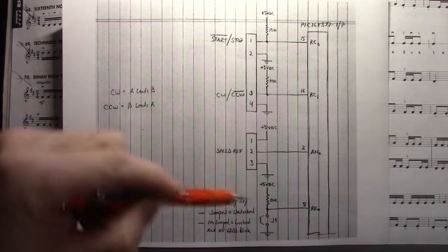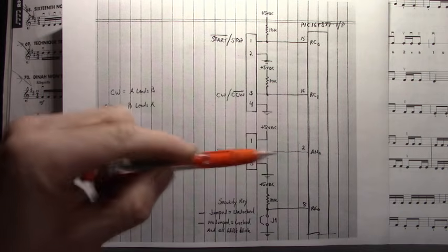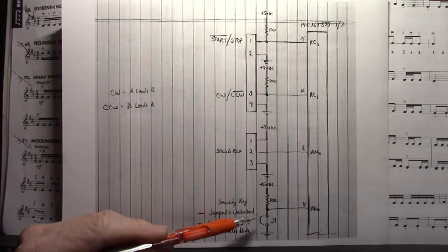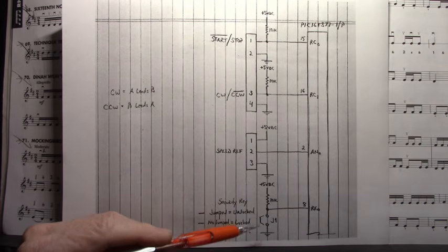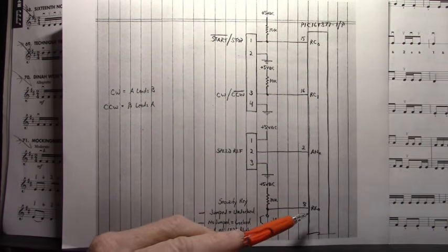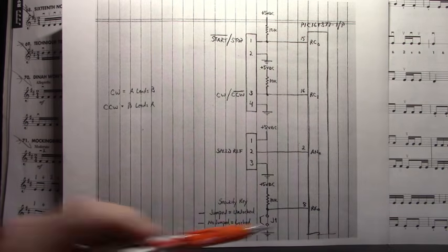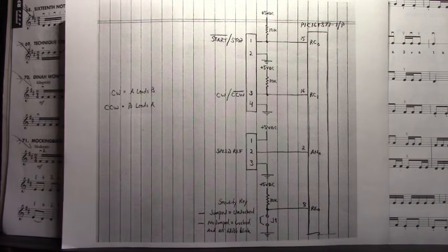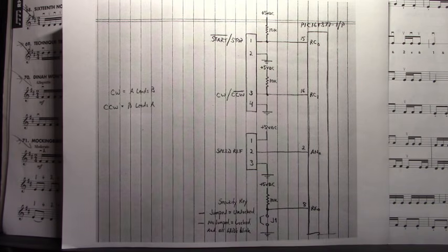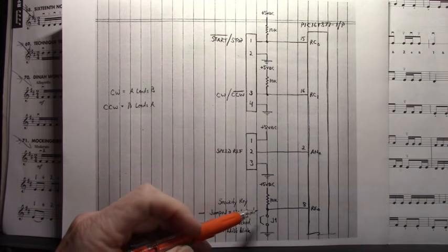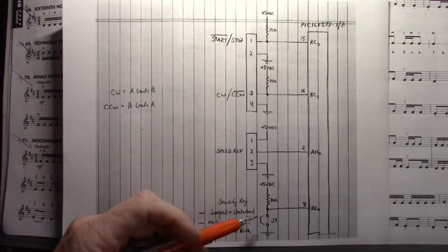We never get to the main structure of the program. The program does not run if this jumper is not installed. When I install the jumper, port E bit 0 is connected to ground, and that allows the program to continue on into the main function of the program. That keeps you from stealing your hardware and running off with it and using it.